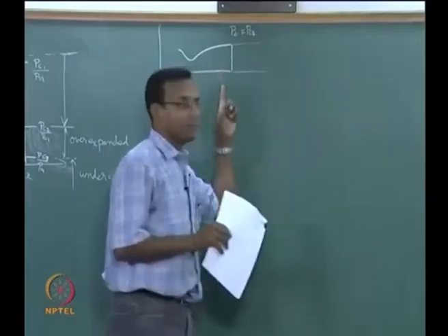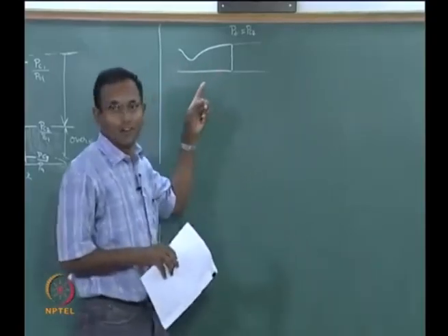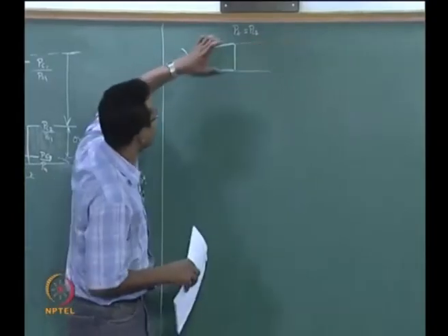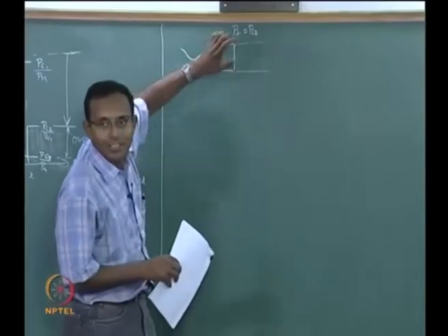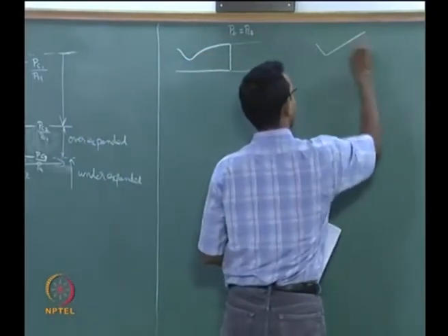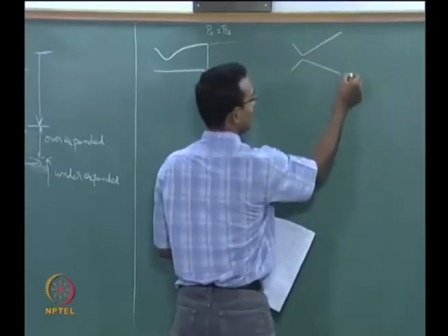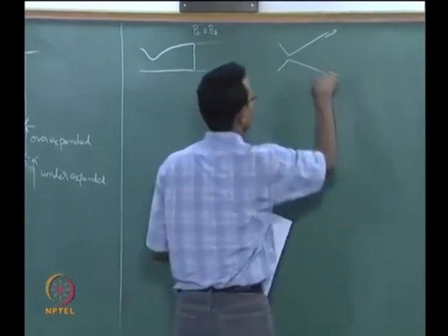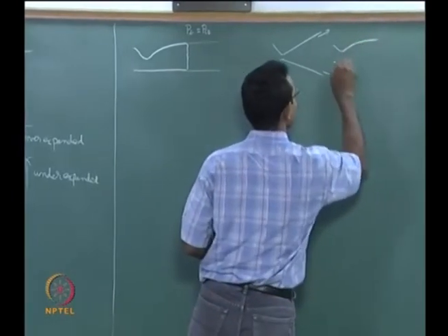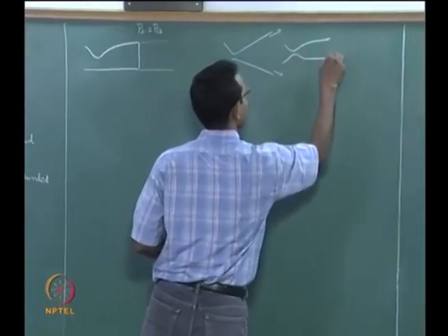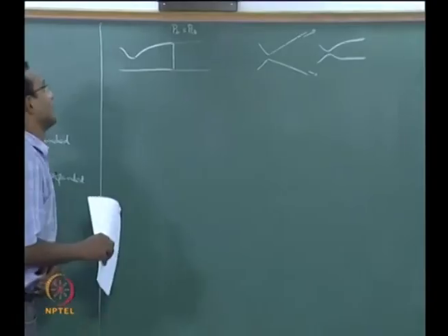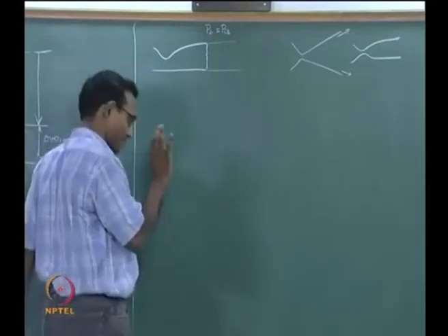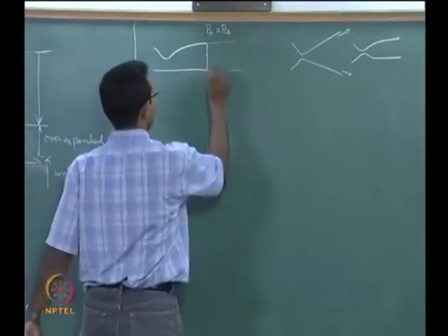I have also done one more thing in drawing this nozzle very carefully. I have drawn it such that the flow is going at one angle only. I have made both the edges parallel to each other. Otherwise, if I have a nozzle that is more like this, now the flow here will go this way, flow here will go this way, and I do not want to be thinking about a 2D problem. So, I will just assume my nozzles will look more like this, exit will always be parallel. Then I do not need to worry about that particular aspect of not-1D kind of thing, it is always 1D in my opinion. We are solving only 1D gas dynamics as of now.